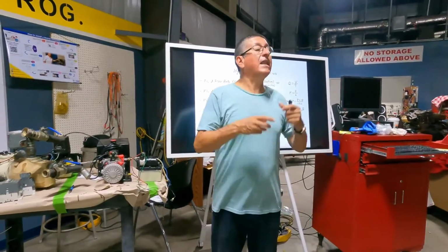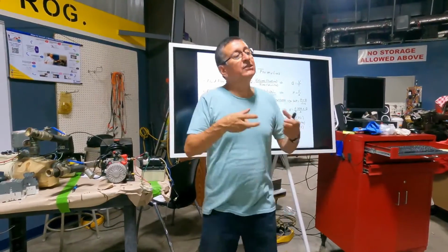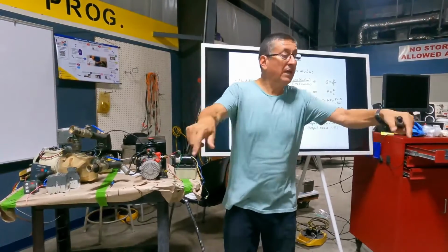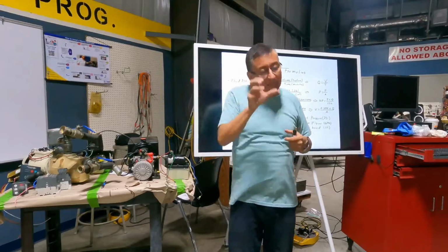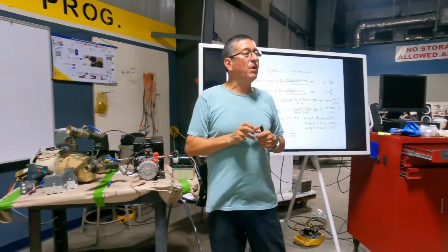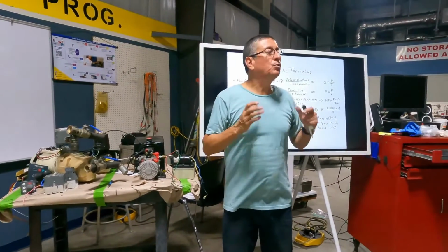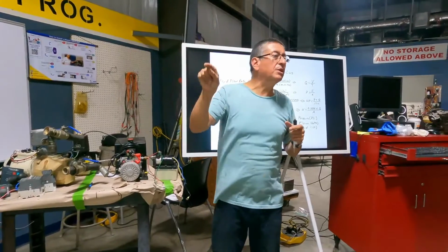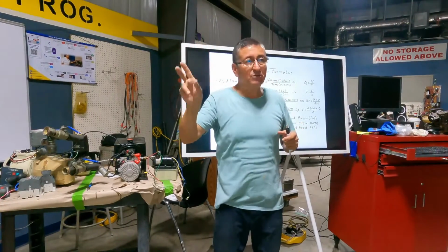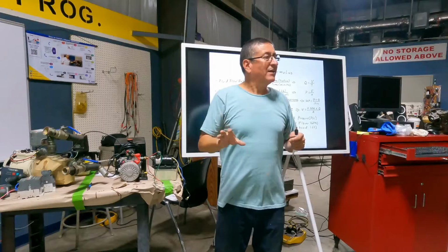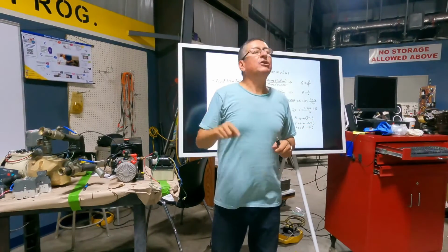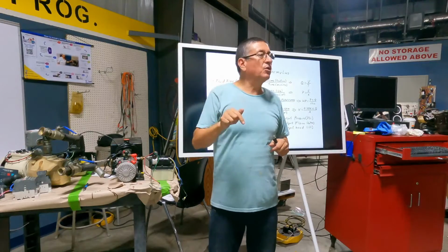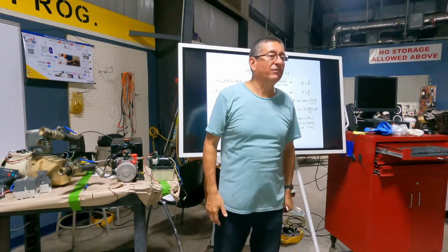You understand? And now with the pump and the electric motor, you can design the container and you create the central hydraulic unit. And now with that electric motor and that pump, you are ready to supply power for those 10 units. Bow thruster, stern thruster, passerelle, tender. It doesn't matter if all of them are working at the same time, because your pump and your electric motor and your reservoir are enough. You understand?